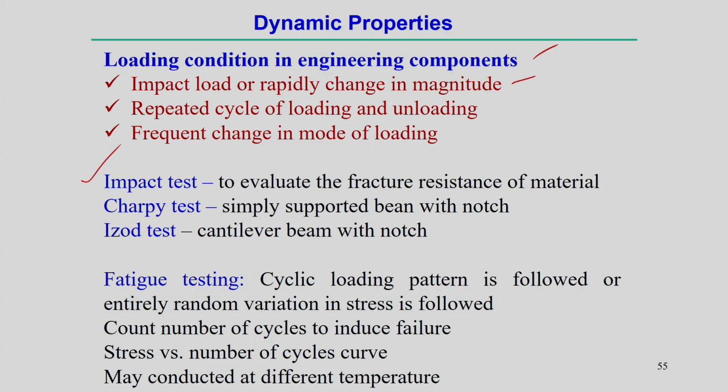The purpose of the impact test is to evaluate the fracture resistance of a particular material. Simply, an impact load is applied to the material and the material fractures, and we normally measure the amount of energy absorbed to fracture that material in the impact testing methodology.